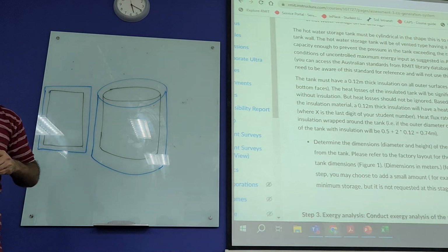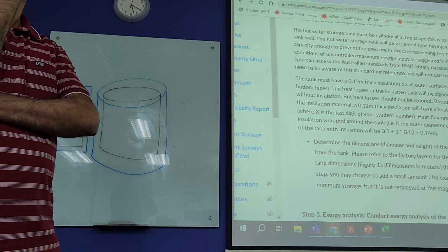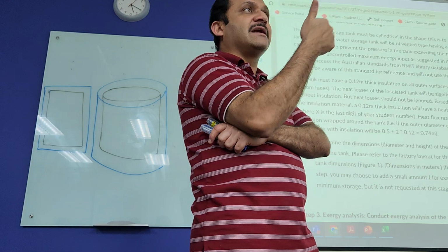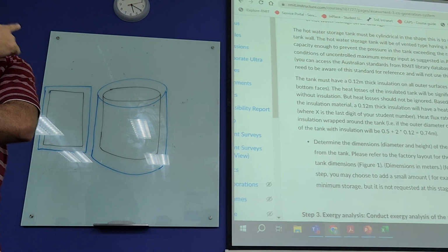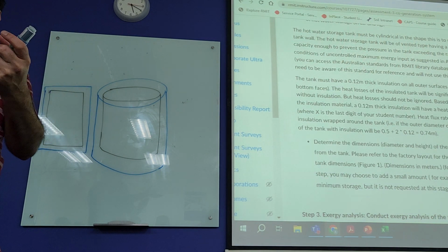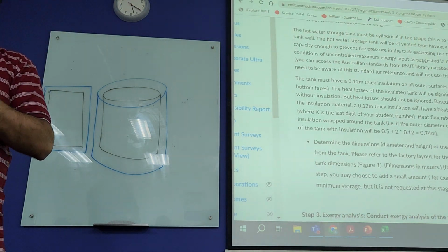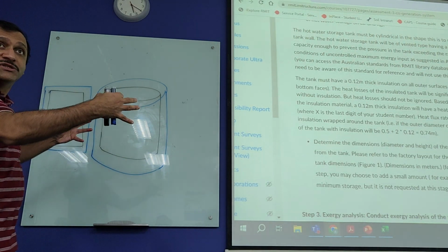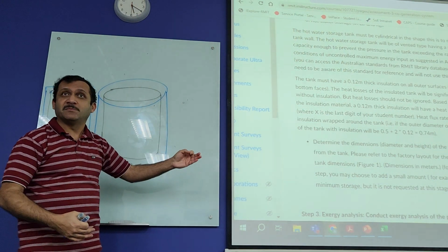Yeah. For diameter, you need to calculate it based on the heat flux usage. Yeah, it's a combination. We need to calculate the size of the tank based on two things. First is definitely that the tank should be able to accommodate the total mass you want to store, right? 500, 600, 700, 800, whatever you got. Plus, you want the size in such a way that the diameter and height combination gives the minimum heat loss from the tank to the surroundings.